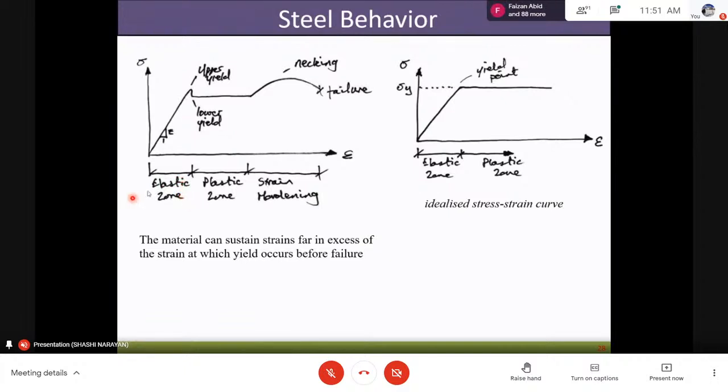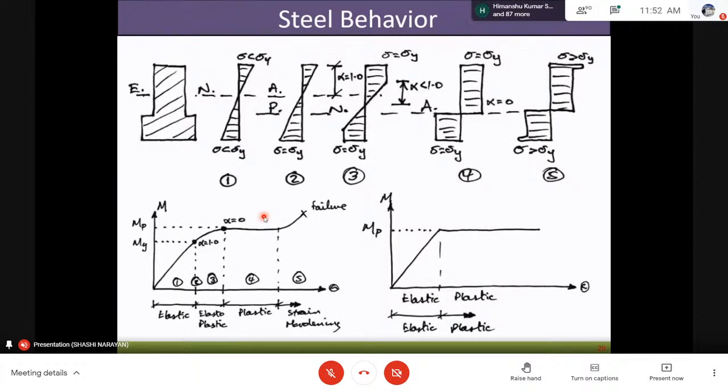And we can compare with the elastic analysis. One may note that the discussion I'm going to do now is mainly for steel structures, not for concrete structures. In concrete structures, there is a variation between the plastic analysis and the nonlinear static analysis. But for steel structures, the nonlinear analysis and the plastic analysis nearly match closely. You would all have gone through this in your third year course.